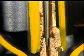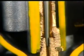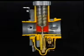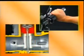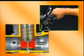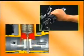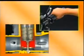Other main parts of the carburetor are the jet needle, which determines the amount of fuel and air used, the various types of jets, and the passages in which they operate. The throttle valve is joined to the throttle grip by the throttle cable. As the grip is turned, the throttle valve moves up and down.